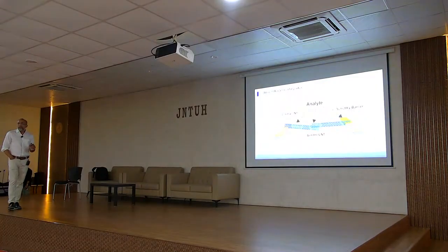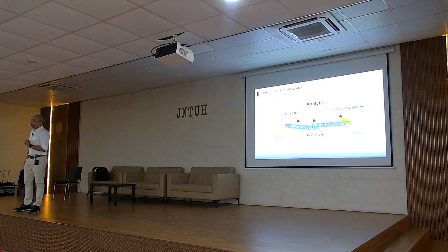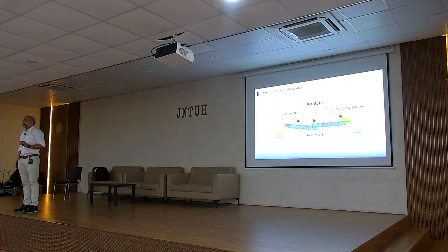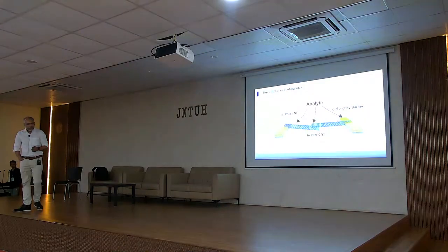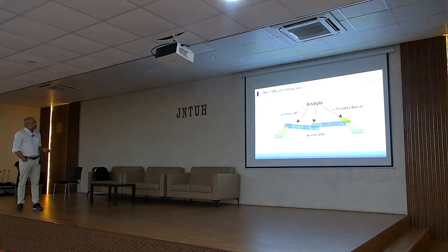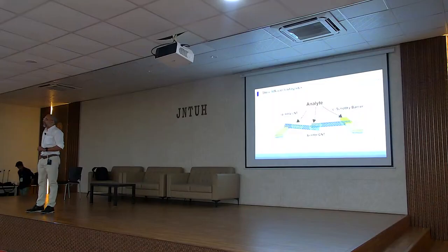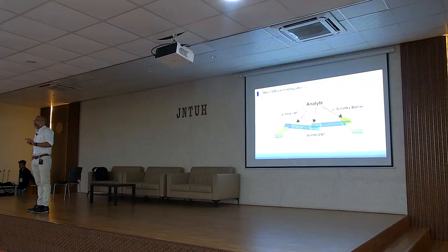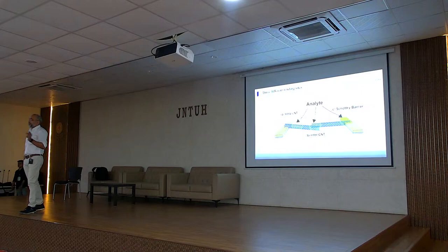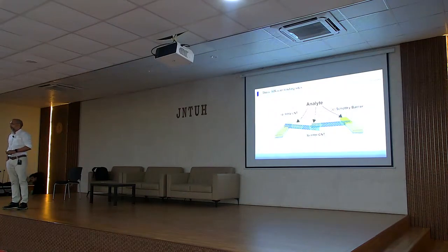So when we talk about sensing, and then we have this carbon nanotube, there are different sites where the analyte will interact. Like first intra-CNT, the second is at the junction of CNTs, and third is at the junction of CNT and electrode. So at least we have three different active sites when we have just only a carbon nanotube network. I'm not talking here about functionalized carbon nanotube or polymer nanocomposite material. I'm talking here just only about a carbon nanotube based network. So we will have at least three active sites.